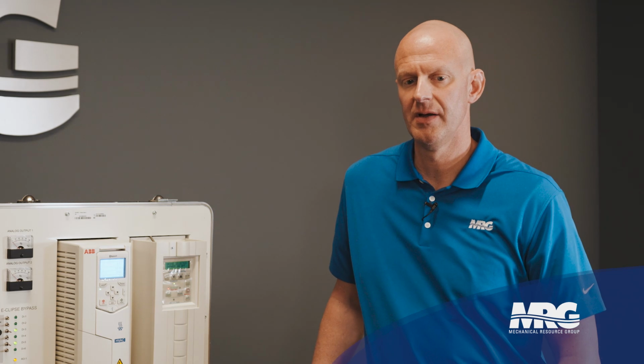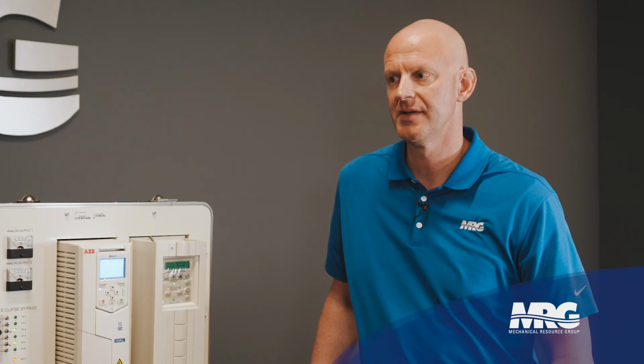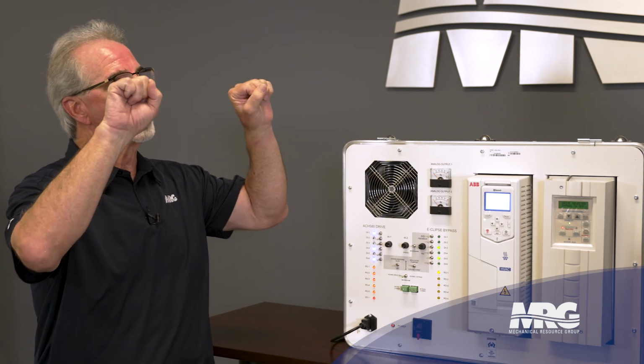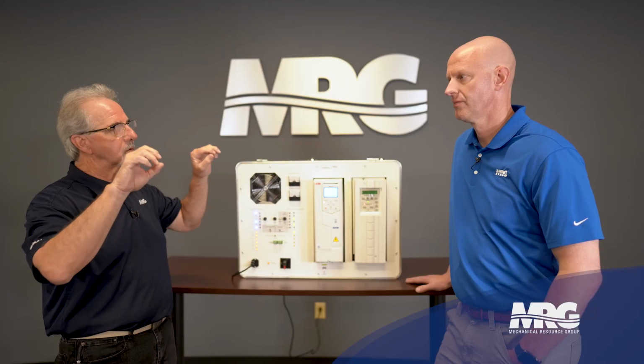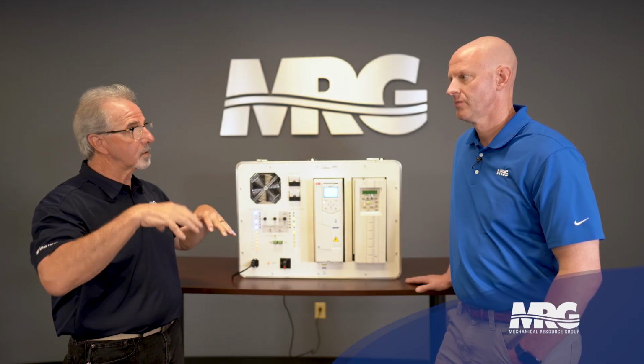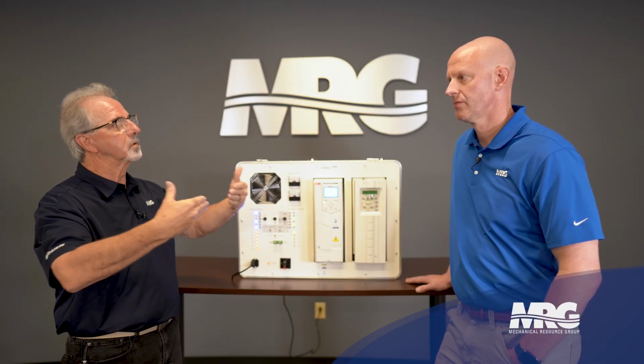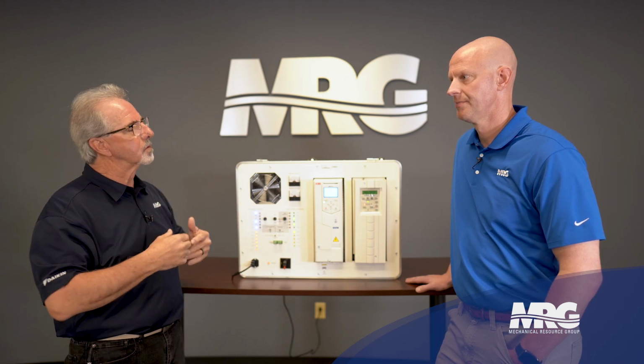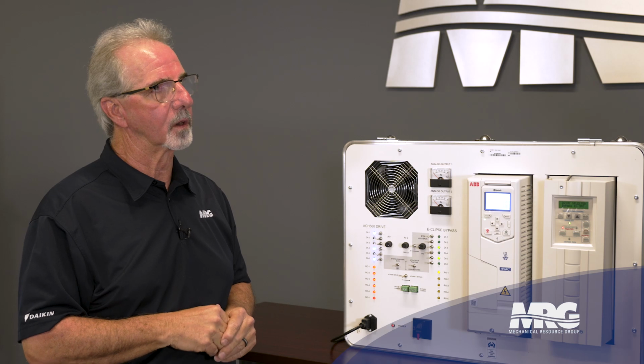Tell me about the over-pressurizing elevator shafts and what that does to the doors. Well, what happened is elevator doors travel on cables. A lot of people think they travel on rails. They don't. They're attached to cables and they're free moving. And so if we put too much pressure inside the shaft, it forces the door to the outside of the frame and the doors won't open and close. So it's really important that you pay attention to what test and balance tells you in elevator pressurization.